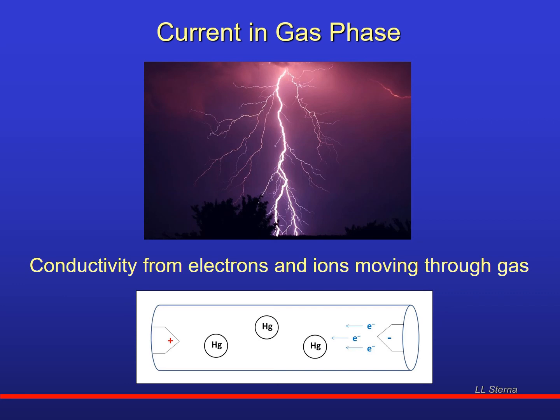When the electrons collide with those mercury atoms, the energy of the collision can excite a mercury atom to a higher energy level. The way that mercury atom returns to its ground state is by emitting a photon, emitting light. The light from those electronic transitions is ultraviolet. That's not going to be very useful for illuminating a room. So that tube has a white powder that absorbs the ultraviolet light and emits visible light.